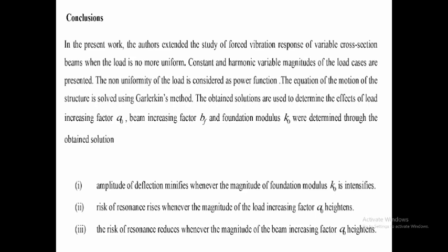Constant and harmonic variable magnitude load cases are presented. The non-uniformity of the load is considered as a power function. The equation of the beam structure is solved using the Galerkin method. The obtained solutions are used to determine the effect of the load increasing factor, beam increasing factor, and the foundation modulus.